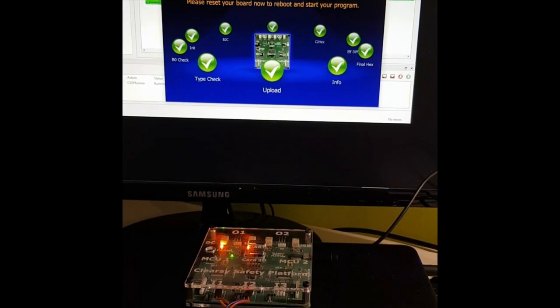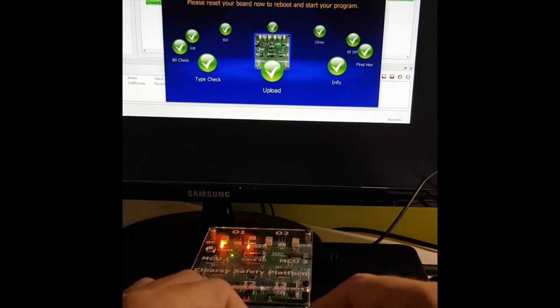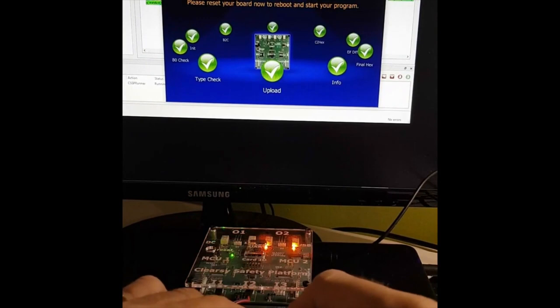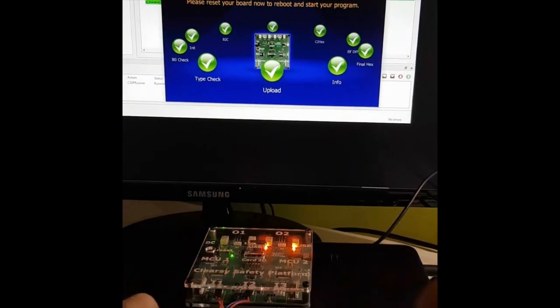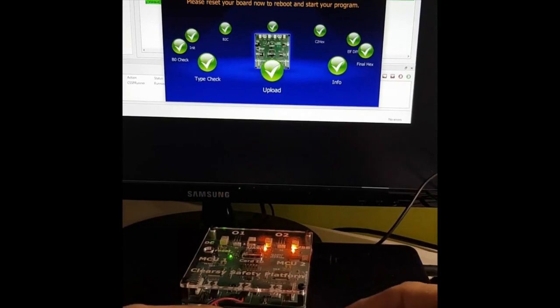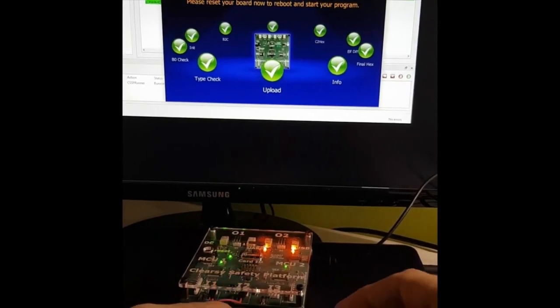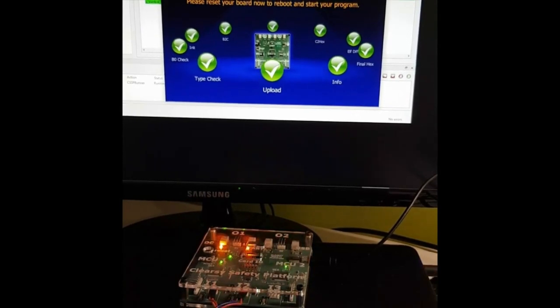And then I will play with my, so I have switches, and I will play with my inputs. And you can see that the outputs have been modified accordingly. So there is a train entering. So the barrier is off and the light is on. And then I'm using the switches to simulate axles leaving and then go back to the previous state.